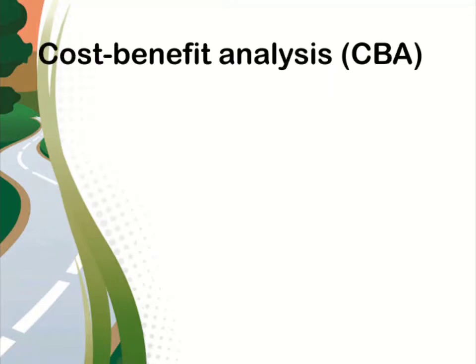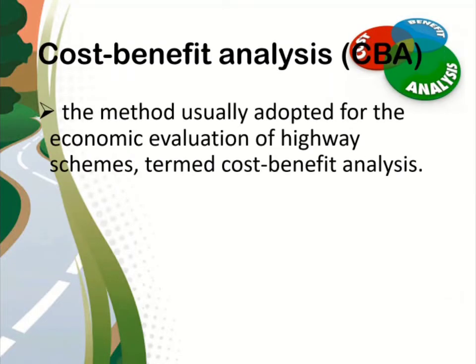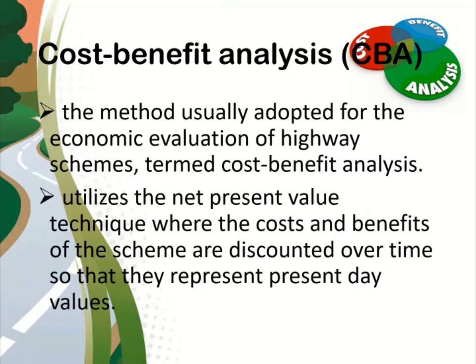The cost-benefit analysis. It is the method usually adopted for economic evaluation of highway schemes. It utilizes the net present value technique, where the costs and benefits of the scheme are discounted over time so that they represent present-day values.